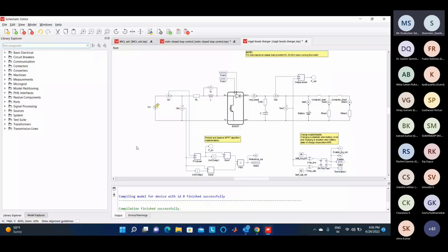And even if it is a microgrid based system, for example PV, wind, and grid connected system, do you suggest generating the control C code for the combined one? Yeah, but you can also use different advanced C functions. What I suggest is to use one, it will be better. But if you want to use two or three advanced C functions, you can, no issue.